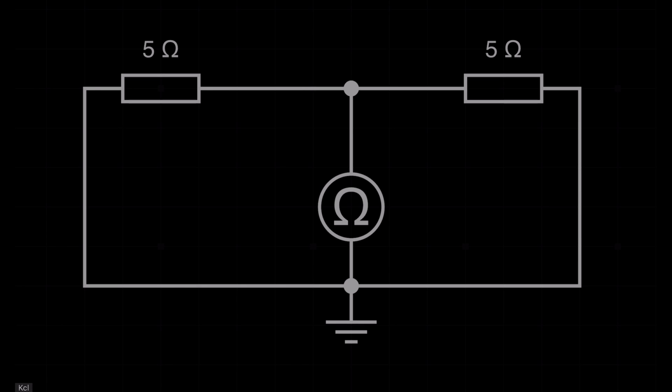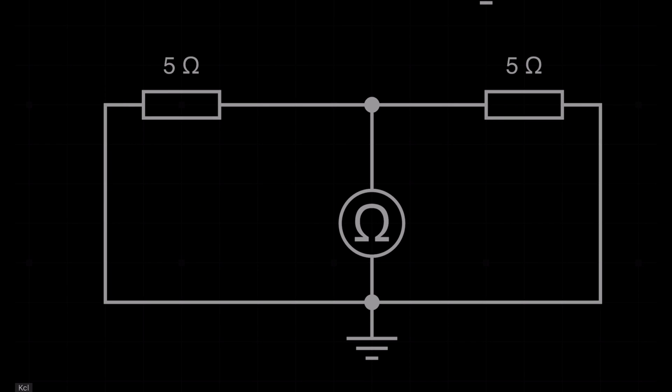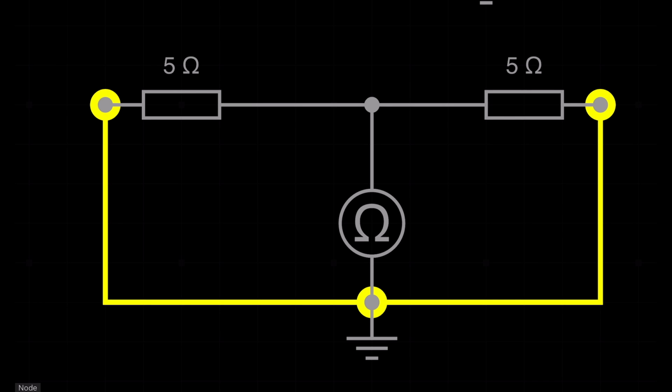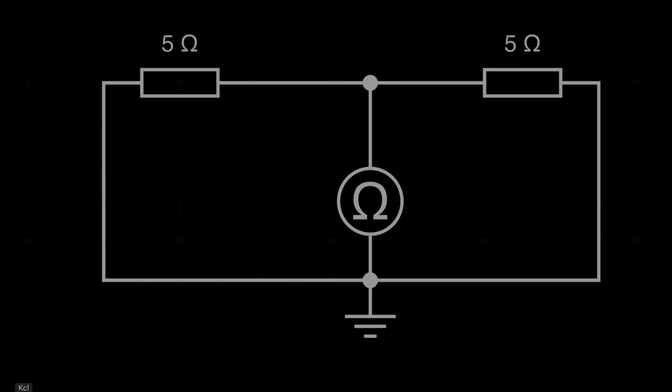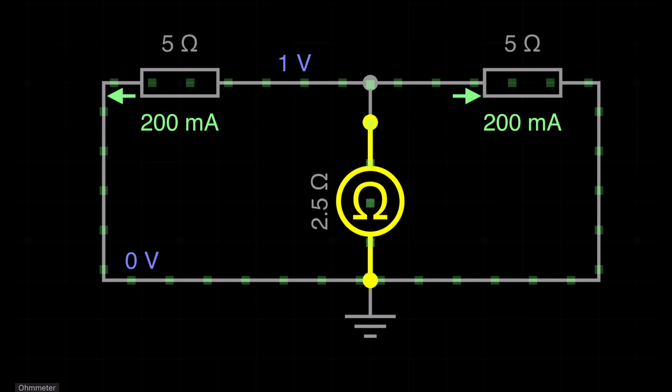Step two, replace the voltage source by its internal resistance. Here we have a voltage source of 15 volt, right? And we already replaced it with the internal resistance of 0 ohm. That's why we made it a short circuit. Now, if I simulate this circuit, this ohm meter will read the value of RTH. Let's simulate this circuit. Here you can see the ohm meter reading is 2.5 ohm, right? That means we calculated the value of VTH as 7.5 volt and RTH as 2.5 ohm, and that exactly matches our simulation result.